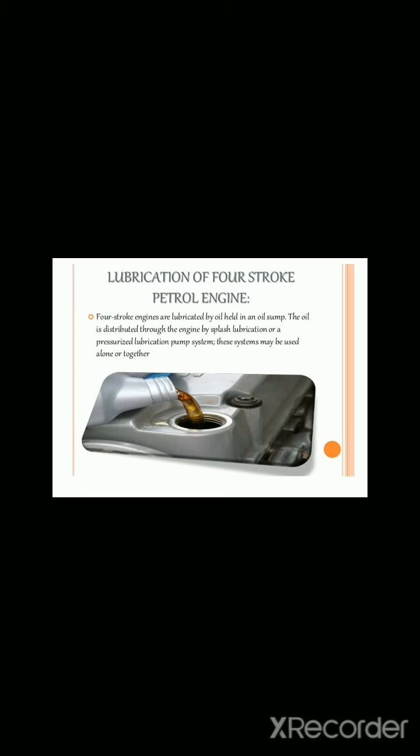Then next point is lubrication of four stroke petrol engine. Four stroke engines are lubricated by oil held in an oil sump. The oil is distributed through the engine by splash lubrication or a pressurized lubrication pump system. This system may be used alone or together.